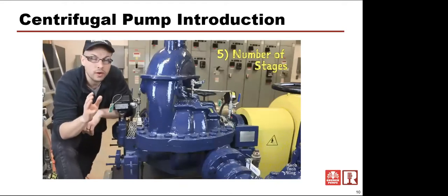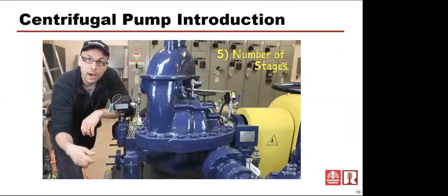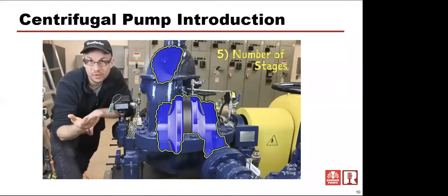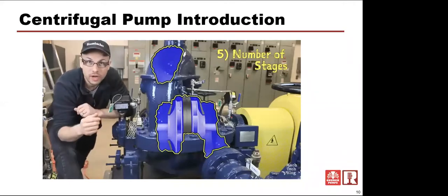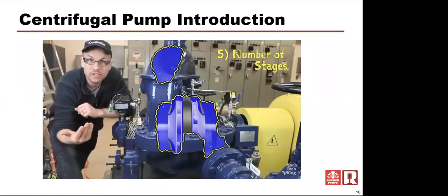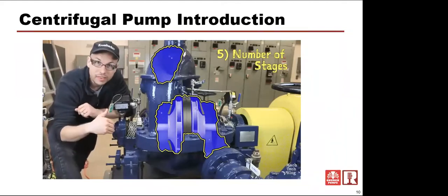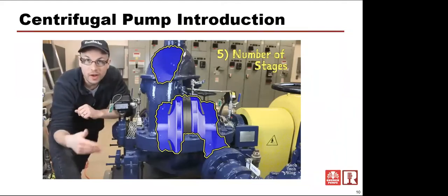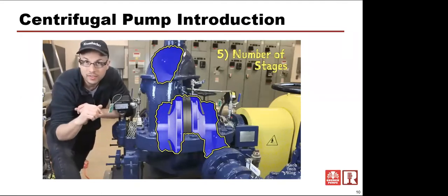Most pumps have one stage with a single impeller and a single volute chamber. However, some pumps have additional stages connected in series to help boost the pump's discharge pressure. The idea is that the first impeller adds energy to the fluid and then feeds it into the next impeller, which adds more energy to the fluid, then feeds it to the next impeller, and so on and so forth until the fluid is eventually discharged into the system.